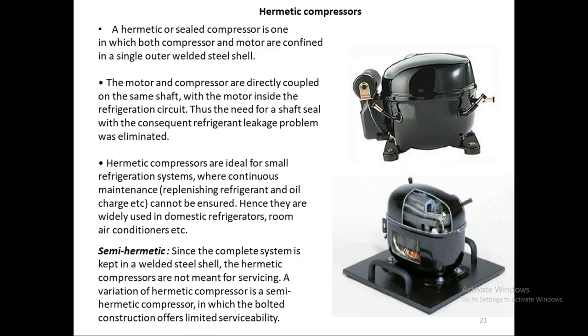The cutout is there. So here it is the compressor and the motor is this one. The compressor is here, somewhere here, and the positive displacement reciprocating compressor is here, and the motor is the down one. This is the stator of that motor. Okay. The motor and the compressor are directly coupled on the same shaft with the motor inside the refrigeration circuit. Thus, the need for a shaft seal with the consequent refrigerant leakage problem was eliminated.